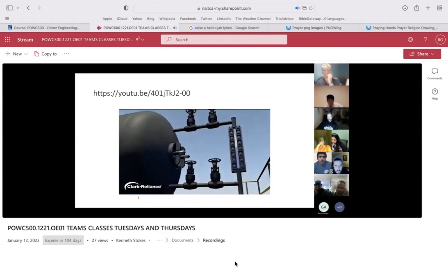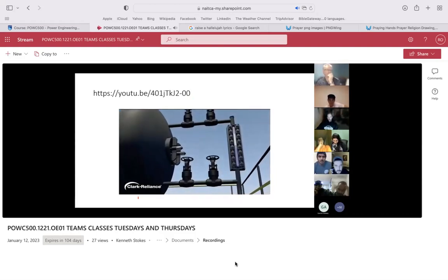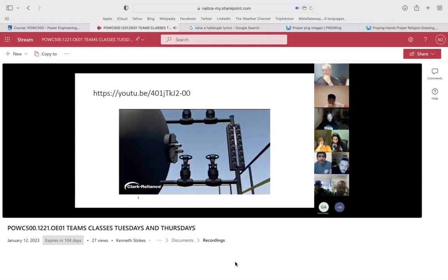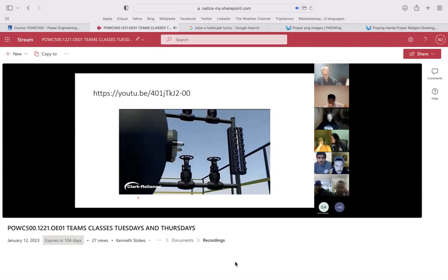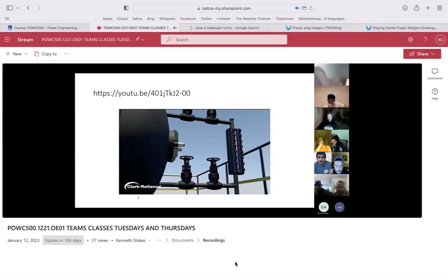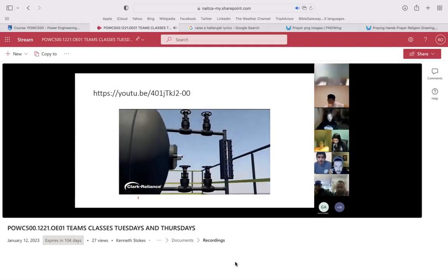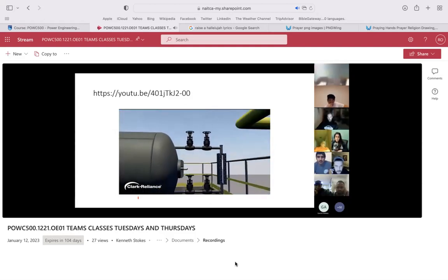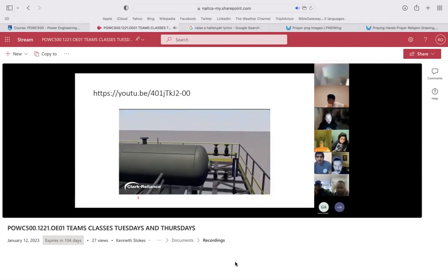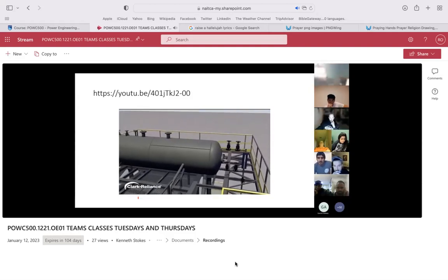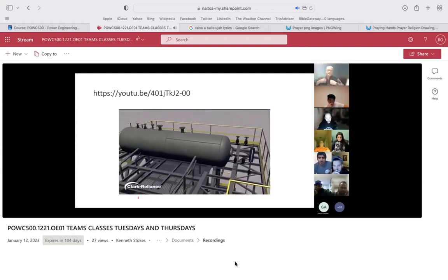The water gauge glass on a boiler enables the operator to visually observe and verify the actual water level in the boiler. However, if not properly cleaned and maintained, a gauge glass can seem to show that there is sufficient water when the boiler is actually operating in a low or low-low water condition. Lack of maintenance may result in a stain or a coating on the inside of the gauge glass where it is in contact with the boiler water and give the appearance of an incorrect level indication, especially if the drum level happens to be outside the range of the level instrument.